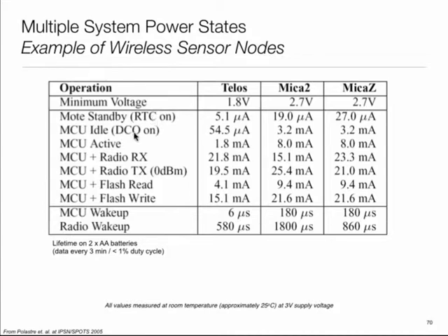The second guy. So here we have an oscillator on, the microcontroller unit is idle, so the processor is essentially idling, it's doing no-op instructions. And what you again see out here is that this guy is pretty darn good. It's like 60 microamp, whereas these guys are into milliamps. And these two numbers are the same because the processor here is the same. So this guy kind of excels. Another thing you would notice is that this guy has a lower voltage, 1.8 volt versus 2.7 here.